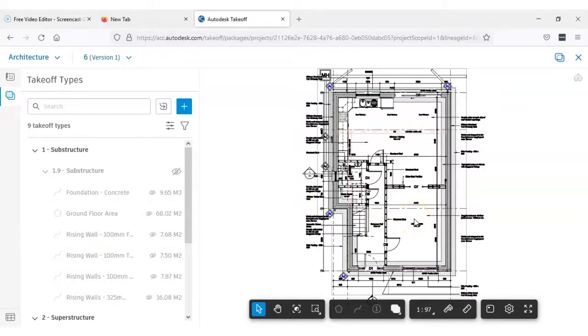Okay, so for example, we could do our calculations based on floor, which is what we're doing at the moment, and then we'd have to maybe add a few different floor items, external wall quantities, for example, into our overall total quantity for external 100mm blockwork. So we have to measure per individual floors. We've got to add them in individually into that one takeoff item.